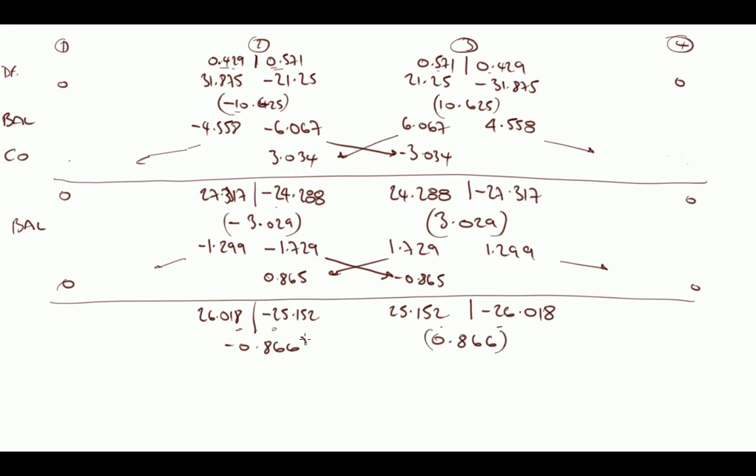Okay, so these are my new balancing moments, and again I distribute those in the ratio of the distribution factors based on the stiffnesses, and I keep reiterating until I finally get a situation where these are, to all intents and purposes, close enough to be considered equal and opposite. Okay, I'll leave it there and leave that for you to finalize for your particular problem.